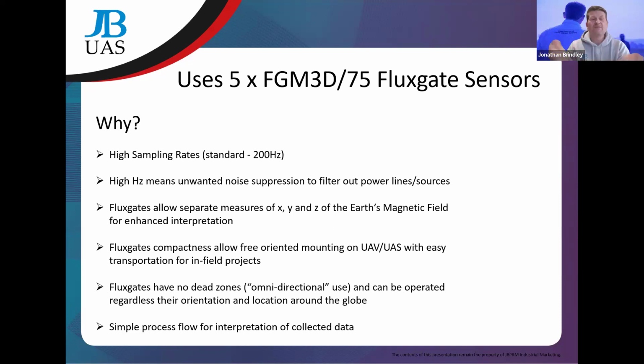Another good reason is that they're really light. When you've had an R4 in your hand, without the recorder it's got a bit of weight to it, but the pole itself has hardly any weight at all. So the fluxgates are really light. That means the whole overall package, even with the recorder, is really easy to move around. It's not cumbersome at all, and that's the last thing you want when you're in the field. So anything that helps you there is a good thing.